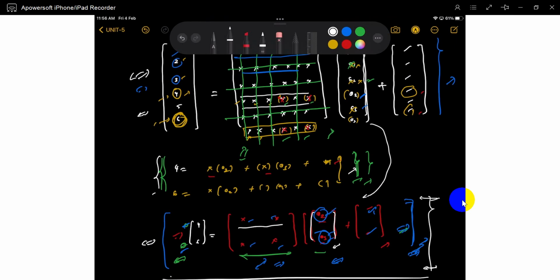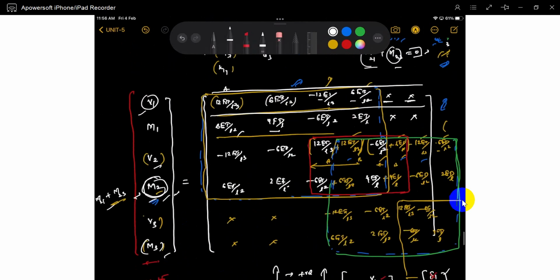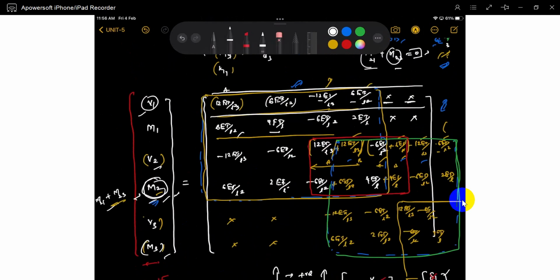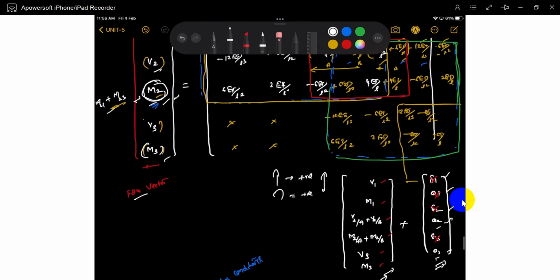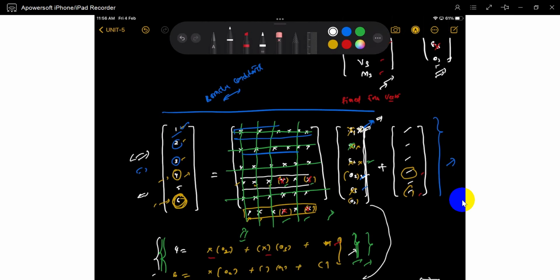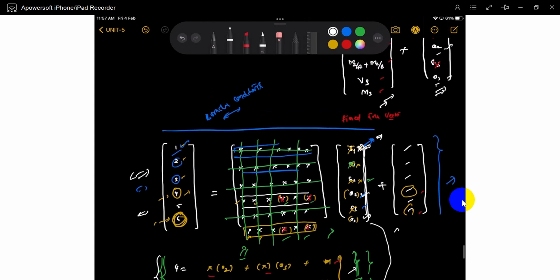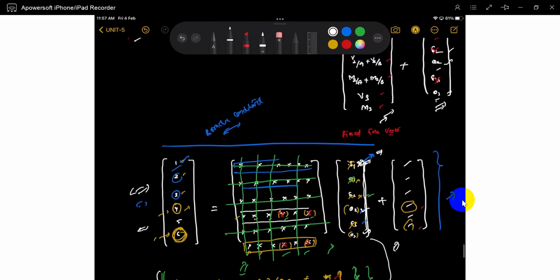Also, I want you to observe the same thing. Here, with a stiffness matrix, the unknowns are not forces. See, what are the unknowns? Unknowns are rotations. Degrees of freedom are the unknowns. If you know the degrees of freedom, you can find out the final moments. Flexibility matrix is exactly opposite. There the unknowns are directly forces. How they developed here, how we come to this conclusion.